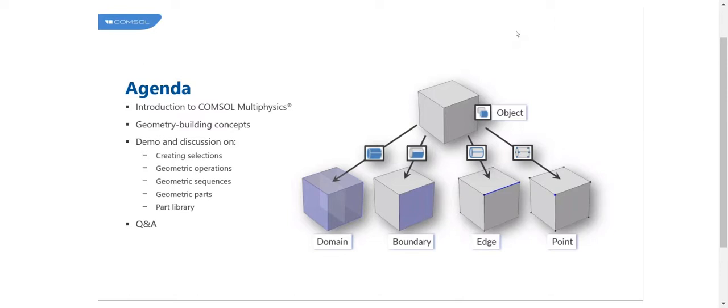This session will provide the introduction to various geometry building concepts such as geometric kernels, geometric entities, and unit conversion. Using the COMSOL Multiphysics software, we will demonstrate the advantage of creating selections and the usage of various geometric operations such as Boolean, partition, form union, and form assembly.